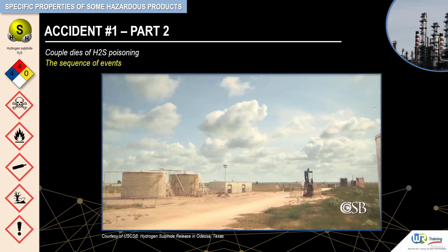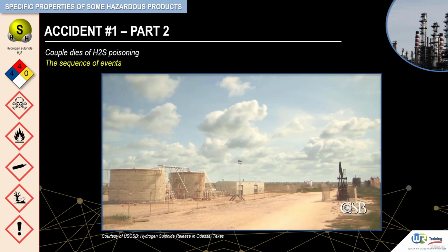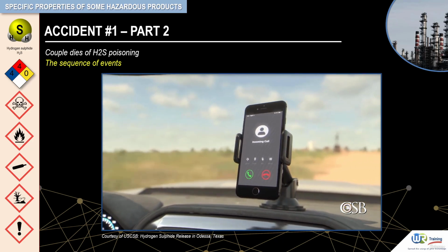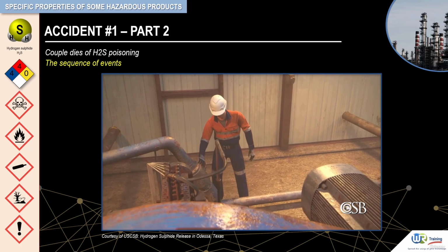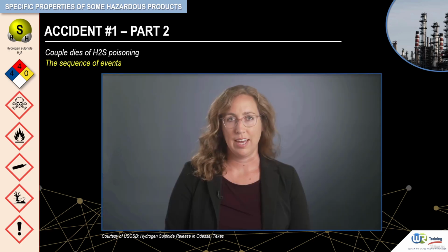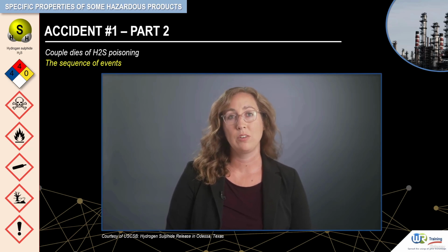At Aghorn, there were no operational, training, testing, and maintenance procedures or records, other than items such as a cell phone use policy and a pamphlet on the hazards of hydrogen sulfide. These items were not sufficient to prepare employees for potential encounters with hazards inherent to their work. At facilities that handle toxic gases, companies must develop and implement a robust safety management program to protect workers and non-employees from exposure to toxic gas.